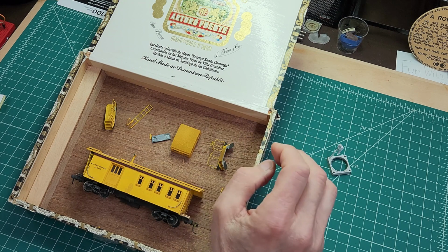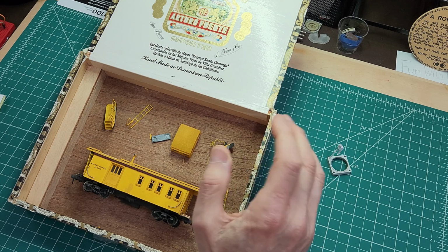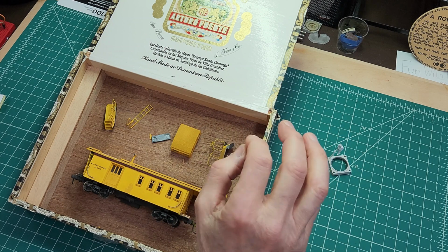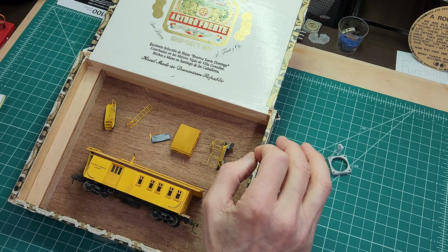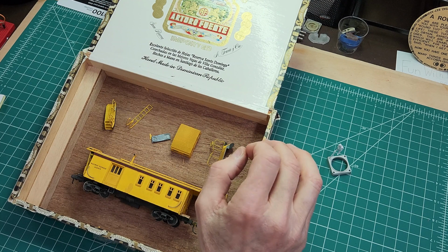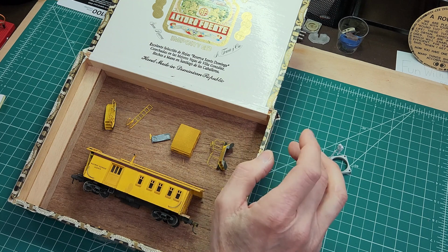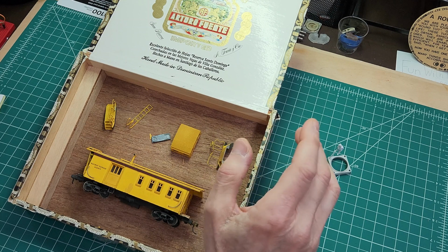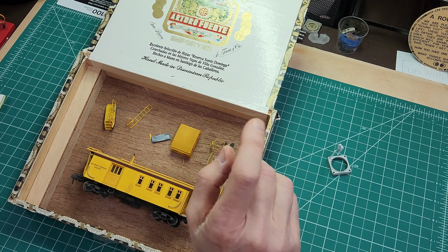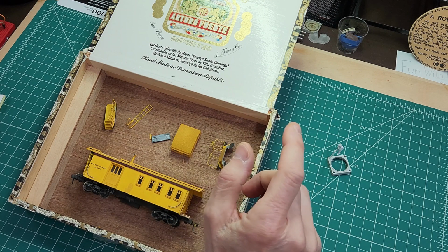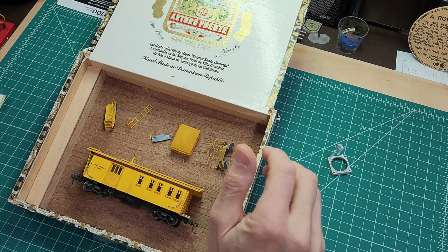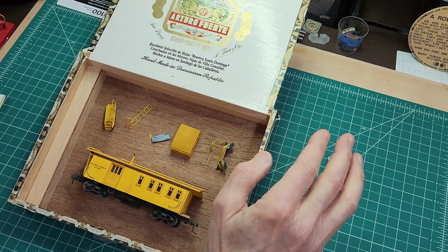Recall that the NCE USB finds the 3 endpoints in addition to the endpoint 0. The execution of the library's get config descriptor calls my driver's endpoint extract for each one of these 3 endpoints. The extract method stores each endpoint descriptor into the driver's endpoint array to be used later for communication with the device. This completes the library task method of connecting to the USB device. Ideally, everything should be ready now for the exchange of data via the USB interface.